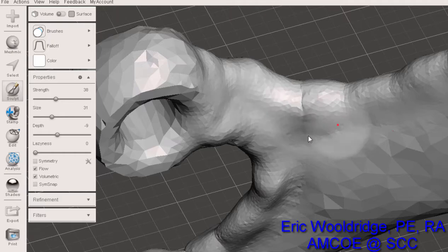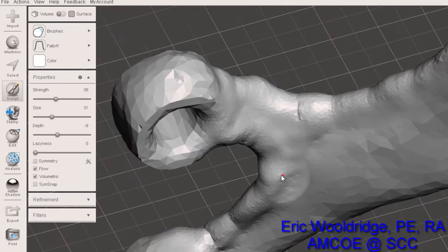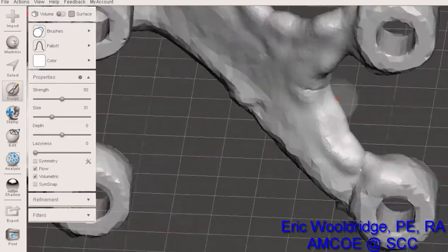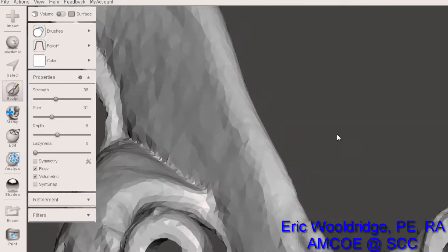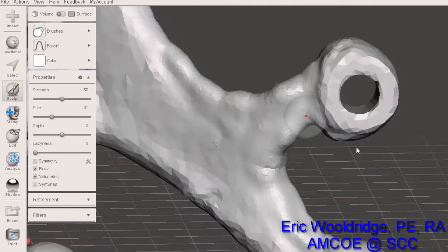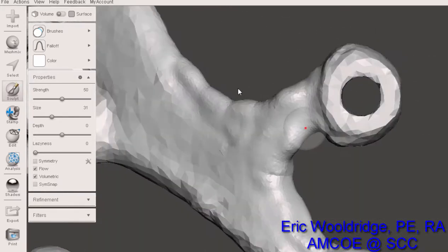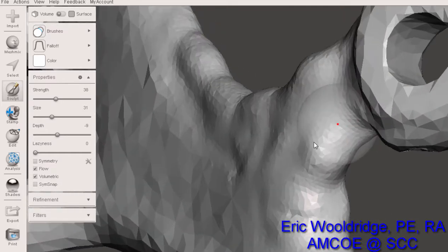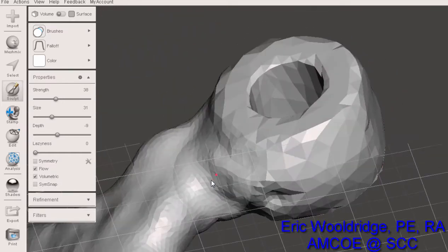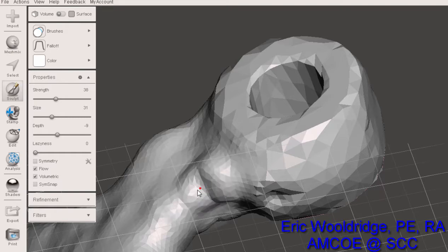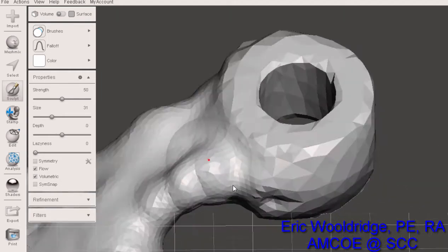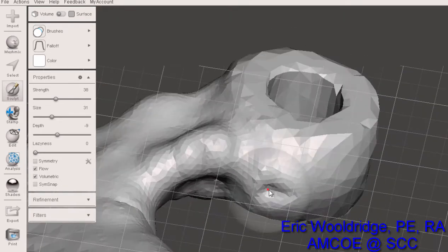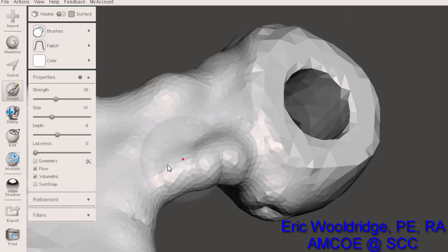You obviously could use finite element analysis software to figure out where your weak points are. But we know from experience that stiffening those edges is going to improve the performance. So what I don't want are little thin zones like what you see right here, even though the generative design may have said, hey, this is the minimum that you need. Sometimes it never hurts to add a little extra in certain zones, just because you know that a condition in reality may be slightly different than it anticipates. And sometimes it just creates an artistic feel for it too.